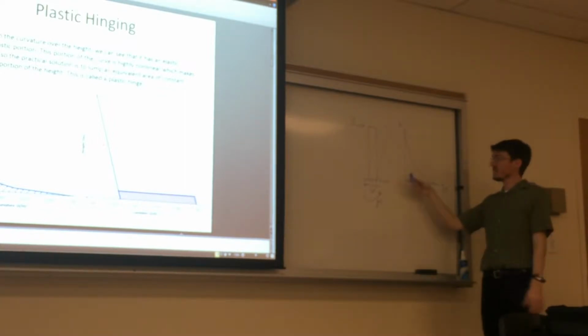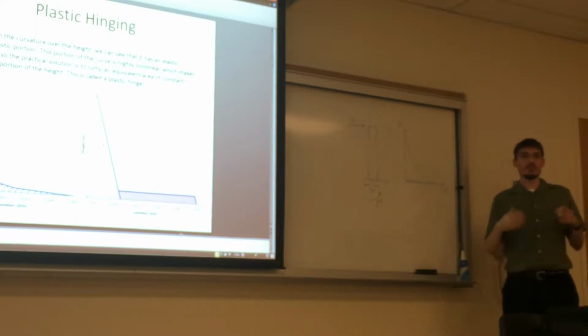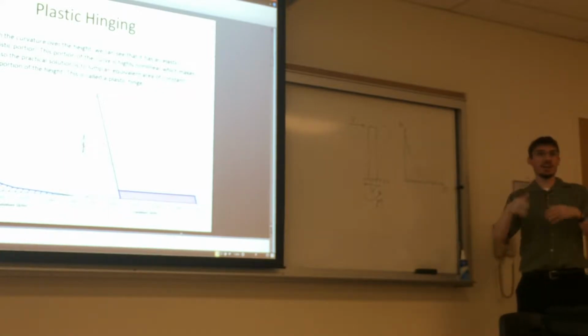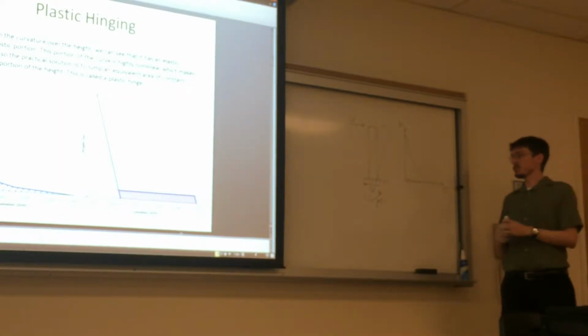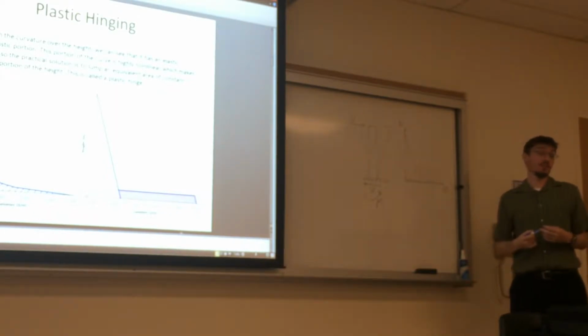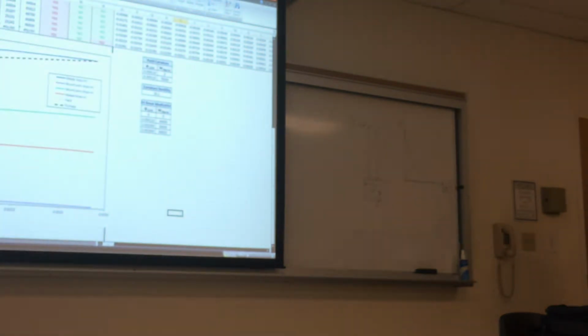So let's say a given guess of curvature. That's something you're interested in, iterating from step to step. You look at curvature when there's zero load, and you look at curvature as your loads are increasing. And then as you're doing that, you're backing out what's the moment capacity of this column for that level of curvature. And then you want to generate, essentially, this plot right here.